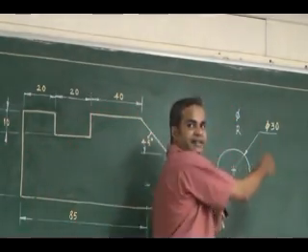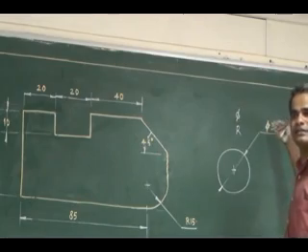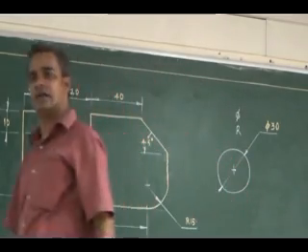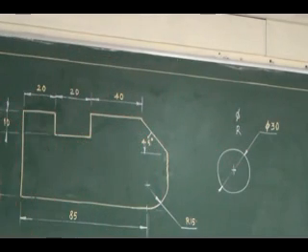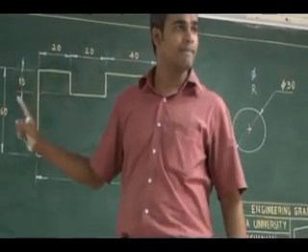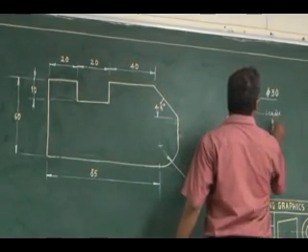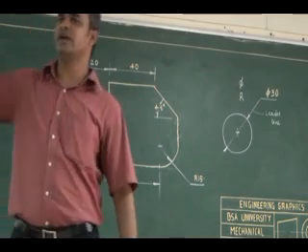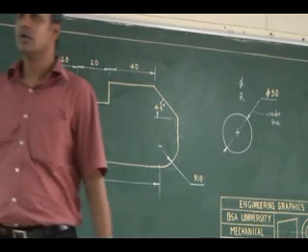Similarly, these two arrowheads I can place inside also. And this angle doesn't matter. The leader line angle doesn't matter. Wherever I have space, along that direction I can extend my leader line. Then I have to draw a horizontal line, over which I place a dimension value. Make a note. Is it clear here? Do you have any clarification in dimensioning? This is nothing but a leader line. For a circle or arc, whatever line we extend from the center is named as leader line, a separate name.